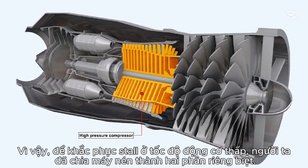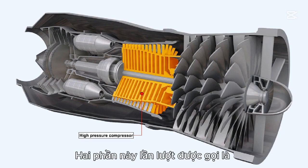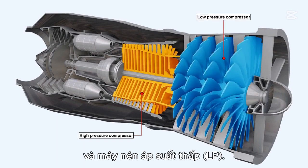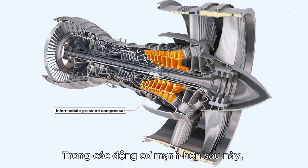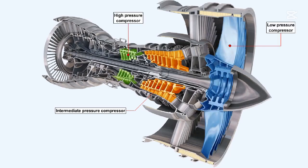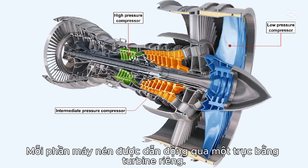So, to overcome the tendency that early axial flow engines had of the compressor stalling at low RPM, designers split the compressor, initially into two separate sections. The two sections were called respectively the high-pressure, or HP compressor, and the low-pressure, or LP compressor. Subsequently, in later, more powerful engines, designers split the compressor into three sections by adding an intermediate pressure, or IP compressor. Each compressor section is driven through a shaft by its own turbine.